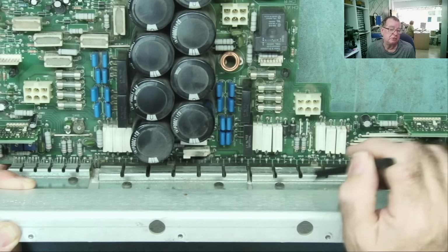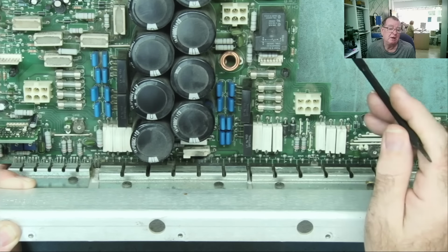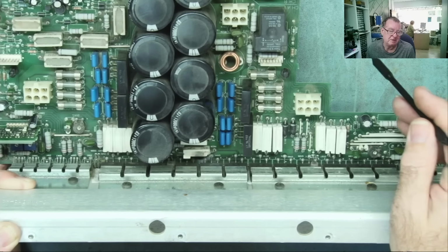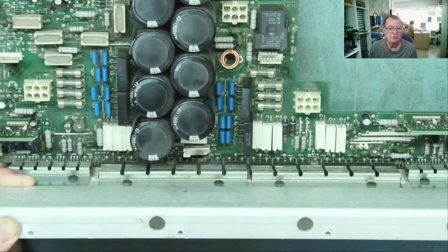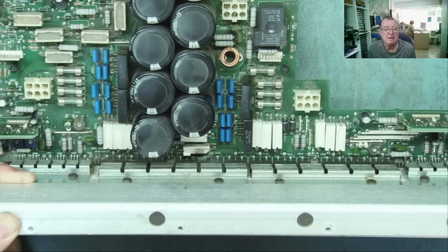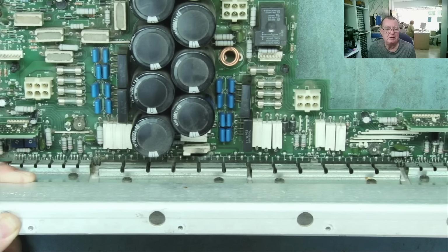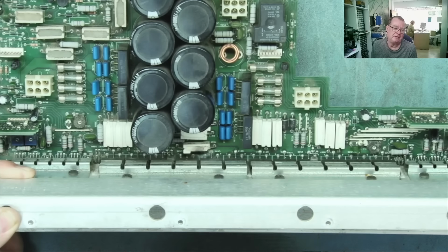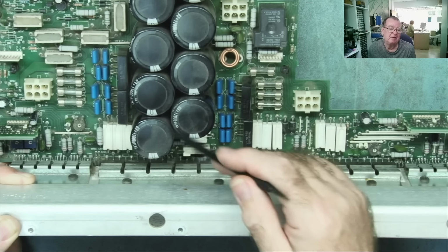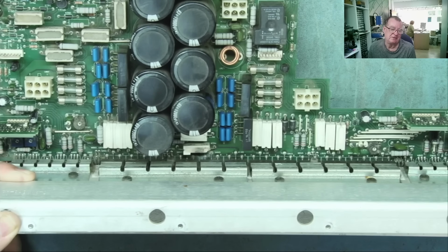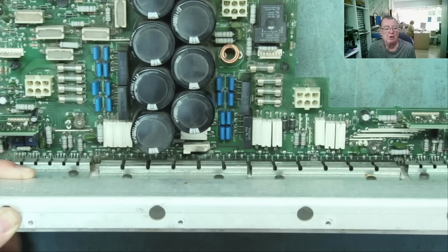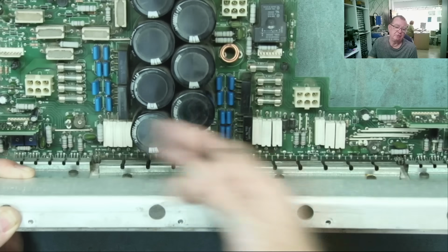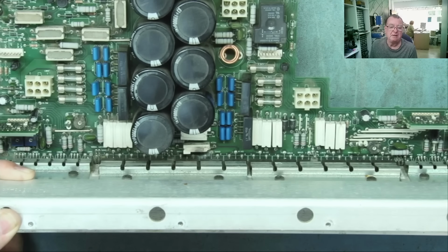Another option, if you're not sure, when you replace the output devices, is to replace the driver devices. If there's an IC controlling this, or a lower powered transistor and then an IC, and if they're not expensive, just change them. The other thing you should really try is maybe slightly less obvious and maybe more difficult, but you should also check what the device is driving. In the case of this amplifier, is the speaker itself short, or the windings burnt out, or completely seized? Because that's what has caused it to fail. Otherwise, although you check all the drivers and the output devices, you plug it back in and it fails again.